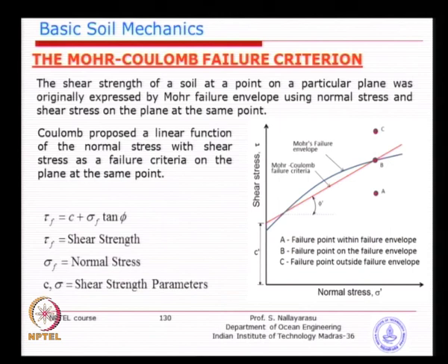So, you can see here it is quite easy to simulate and predict the stresses, because it is made as a straight line with an intercept of the shear strength, which is something that we derived earlier. If you look at this equation, it is a component of adhesion plus the part of the shear stress as a failure criterion coming from the normal stress. So, basically this gives a linear principle in comparison to the original failure criterion, which is curvilinear.